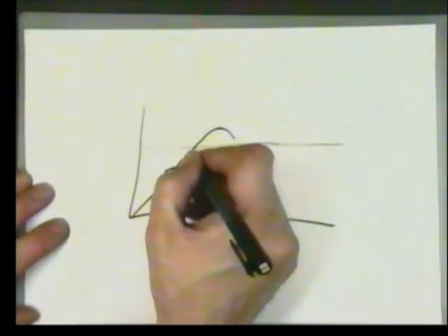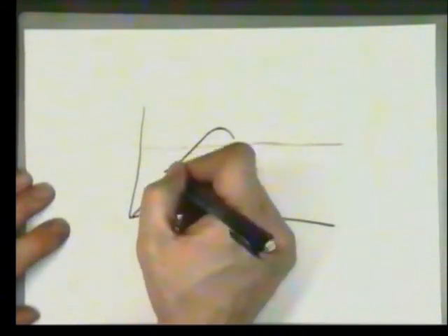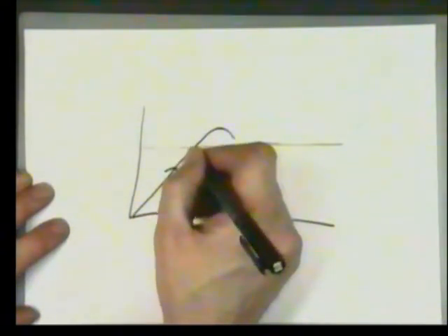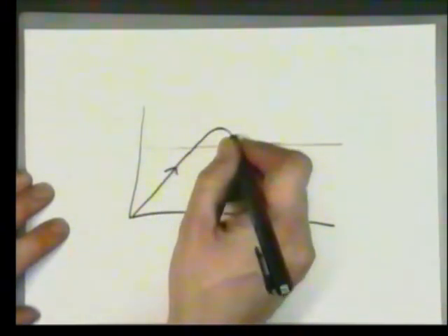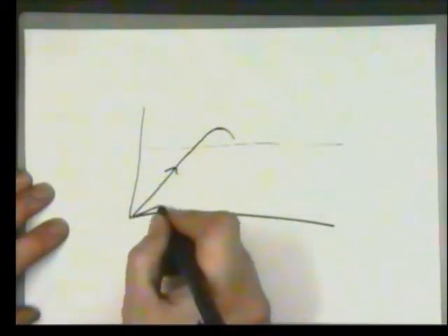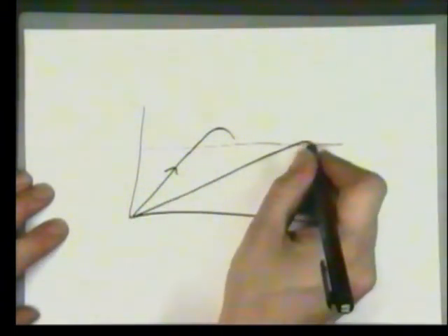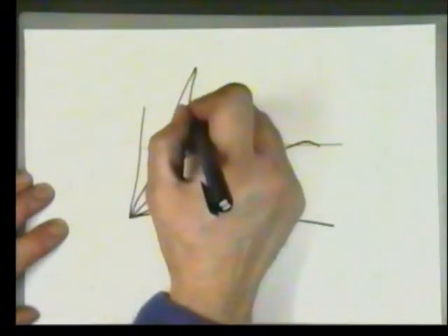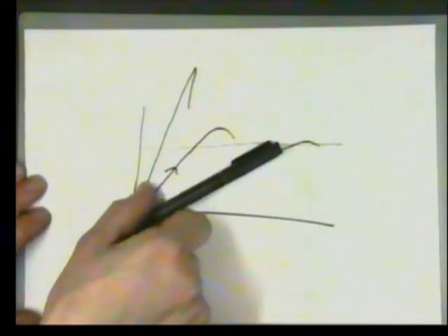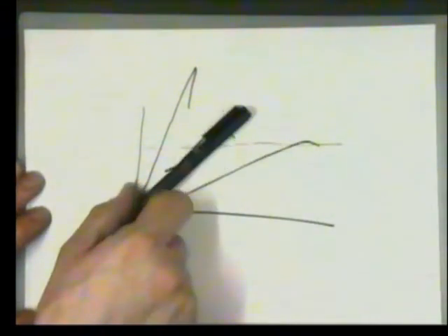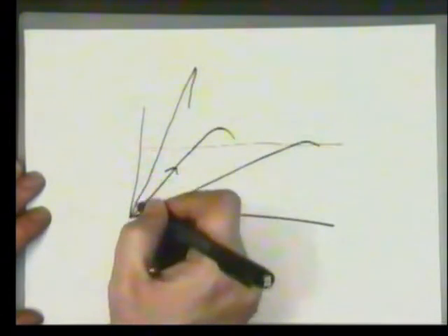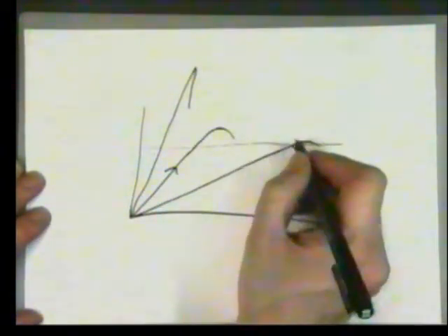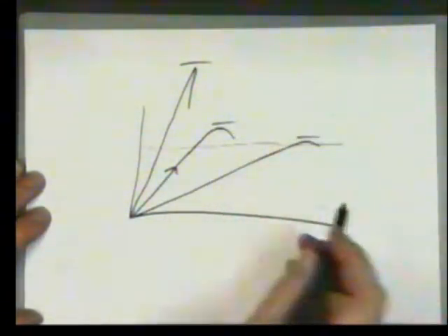Now what we could say is, look, if we were to measure the rate of that slope, that would give us an indication of how bad the slippage, the overshoot, will be. If we had a very gradual slope, we're more likely to do that. If we had a very steep slope, we're going to get that. So there's a relationship between the rate of change as you approach the set point and how far you will overshoot before you start coming back down. And there is a measure of our error.